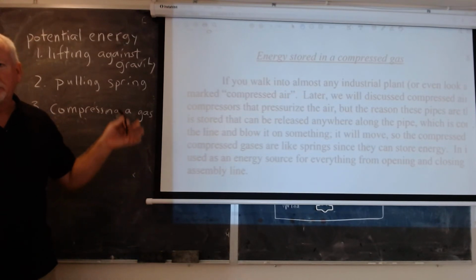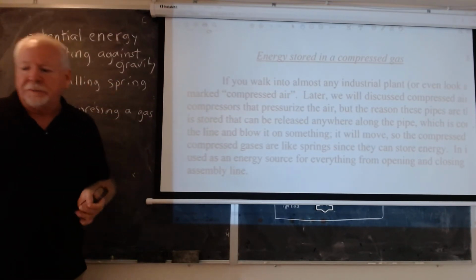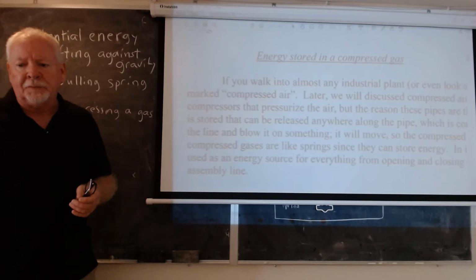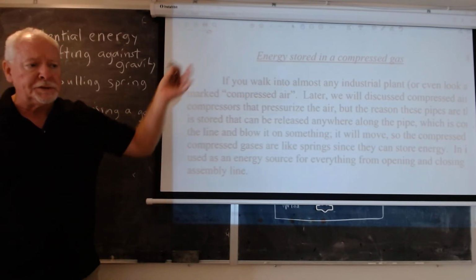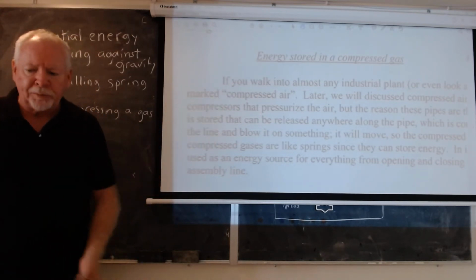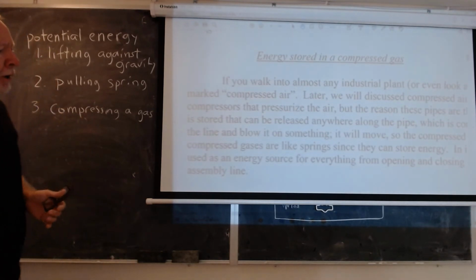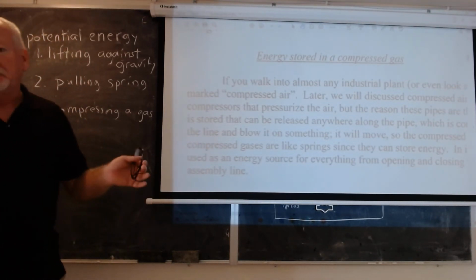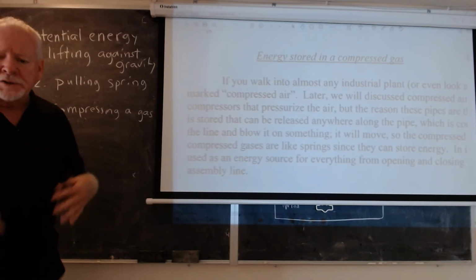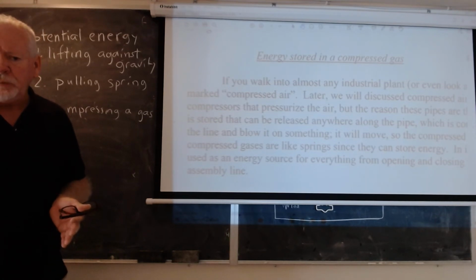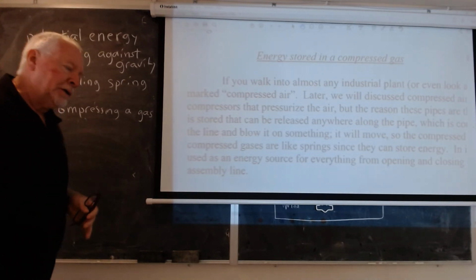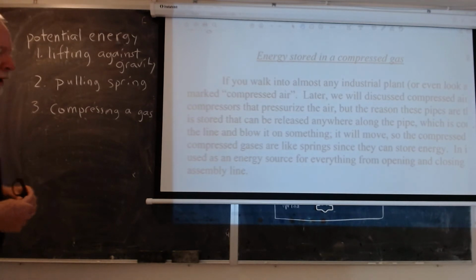whereas these examples like lifting against gravity are very efficient, right? When I lift it, very little energy is wasted in performing that. Even if you were pumping water up a system, very little energy is wasted. The fraction of energy you can recover by that water going back through a turbine is very high. Compressed air, you get about 15%, meaning as you compress the air, you're wasting about 85% of your energy. And how it's being wasted is you're heating up the air while you're compressing it, which, as we go through this, you'll find is thermodynamically unavoidable.